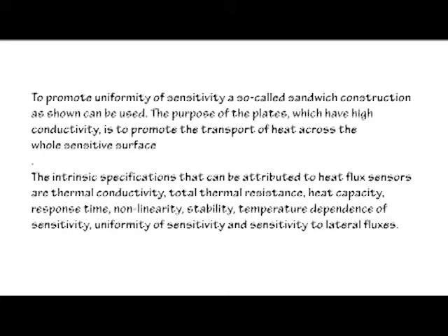To promote uniformity of sensitivity, a so-called sandwich construction, as shown, can be used. The purpose of the plates, which have high conductivity, is to promote the transport of heat across the whole sensitive surface. The intrinsic specifications that can be attributed to heat flux sensors are thermal conductivity, total thermal resistance, heat capacity, response time, nonlinearity, stability, temperature dependence of sensitivity, uniformity of sensitivity, and sensitivity to lateral fluxes.